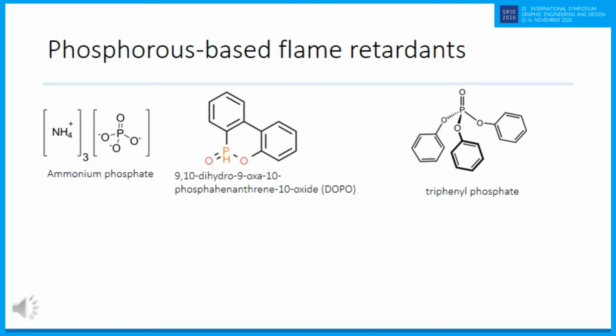Phosphorus-based flame retardants, both organic and inorganic phosphorus compounds, provide flame retardant properties for many polymers. These compounds are actively used in the industry as a reactant and additive. In addition, certain flame retardants based on specific phosphorus compounds, such as methylphosphonate, may have negative effects on burning, forming phosphorus and phosphate radicals in the gas layer.